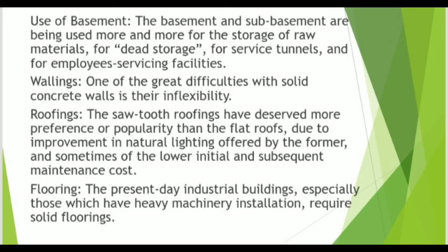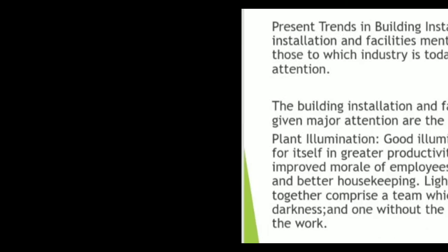Walling. One of the great difficulties with solid concrete walls is their inflexibility. Roofing. The saw-tooth roofings have gained more preference or popularity than the flat roofs, due to improvement in natural lighting offered by the former and sometimes the lower initial and subsequent maintenance cost. Flooring. Present-day industrial buildings, especially those which have heavy machinery installation, require solid floorings.